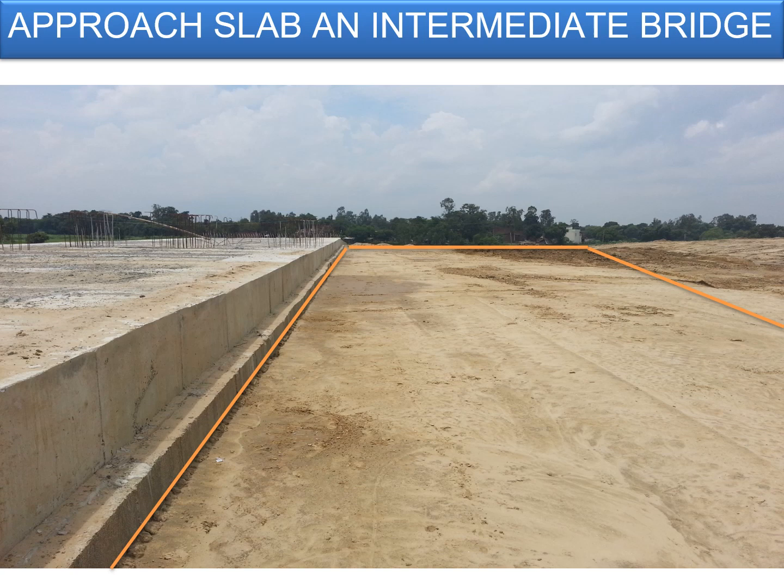On the right hand side, the line demarcated with an orange line shows that when the road is being constructed, it has been constructed up to the right orange line initially along with the main carriageway, and then this gap demarcated with the orange line is filled up after the completion of the bridge. So this is the portion which is an intermediate span, getting filled up after the completion of the bridge.